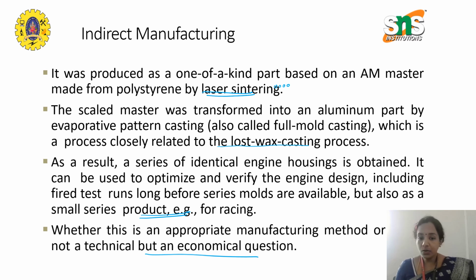As a result, a series of identical engine housings is obtained. Whichever shape or product we want, we can get it from the molds and also from the impressions. This can also be used to optimize and verify the engine design test runs before series molds are available, but also as a small series product, for example for racing. Whether this is an appropriate manufacturing method or not is a technical or an economical question.